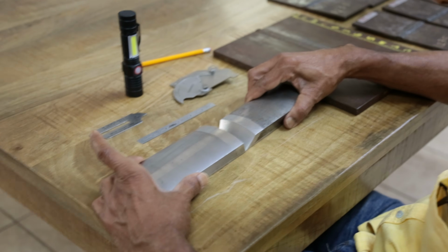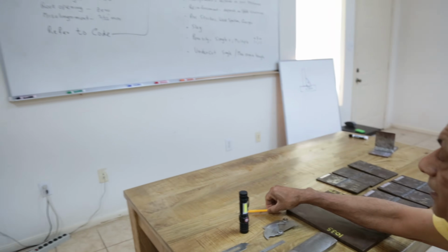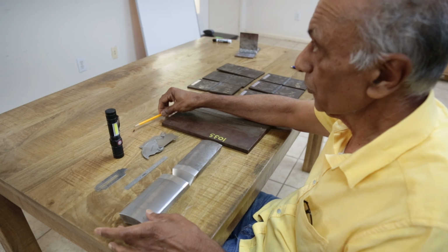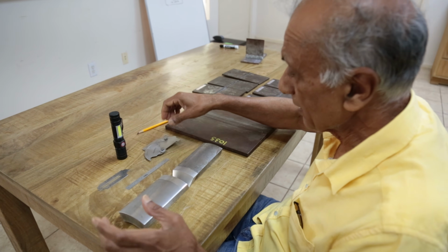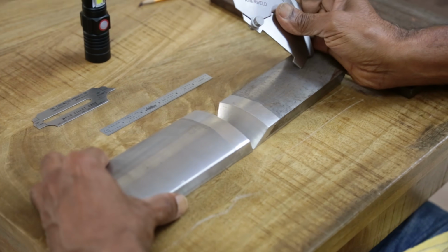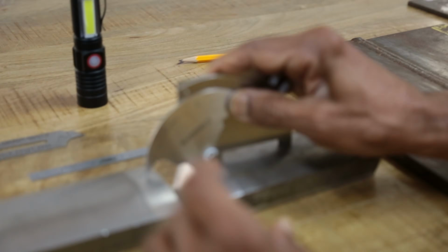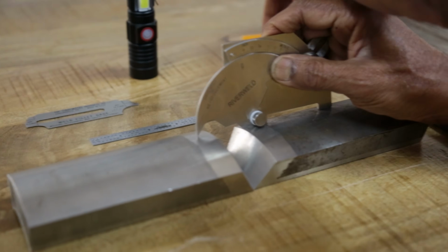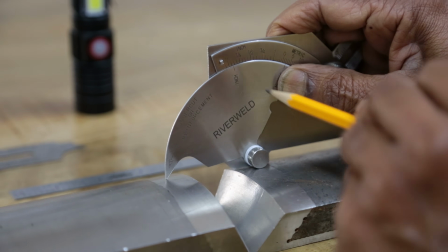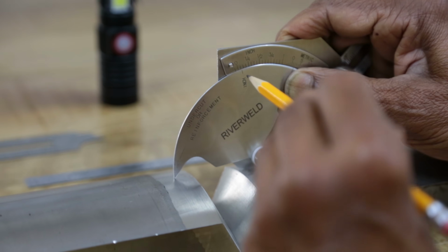So now we have not started the weld. So we are on the left side of the board there, in which we are preparing to do the welding. So that gives you a root, bevel angle and misalignment and all that. So let's check for the misalignment. The welding has not started, and these are some samples I have with me. So you put it here, and then from there you can actually see how much is the misalignment right there. So whether it is acceptable or not. So you put the gauge on one side and this pointer on the other side, and it tells you the misalignment.